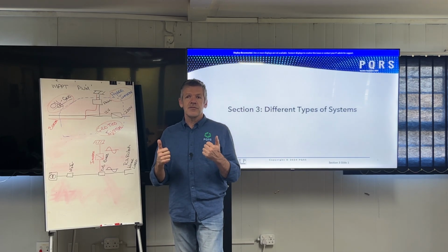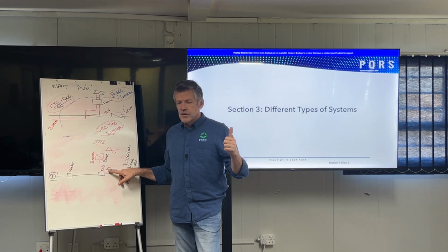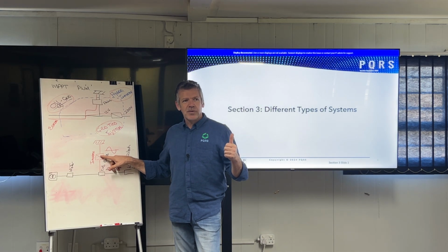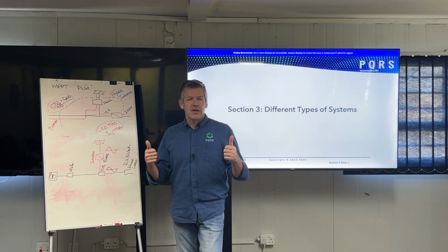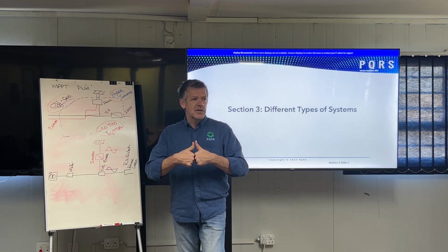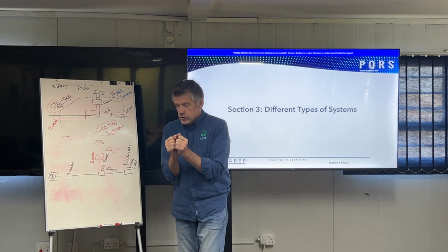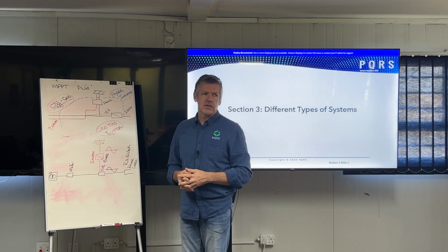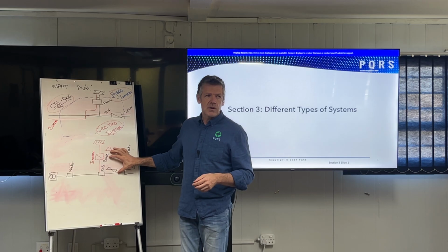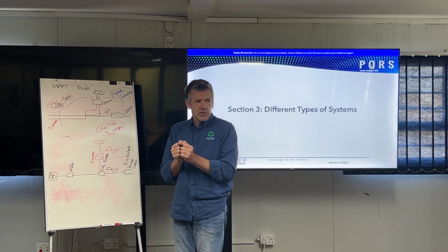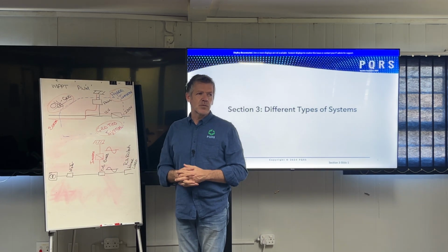I call it the grid's fingerprint. So the grid has a fingerprint. When this inverter wakes up, it starts looking for this fingerprint and it wants to copy it. As soon as it has copied it, it synchronizes. It holds onto the fingerprint of the grid. And as long as it has something to hold onto, it will be able to push power into the DB board.